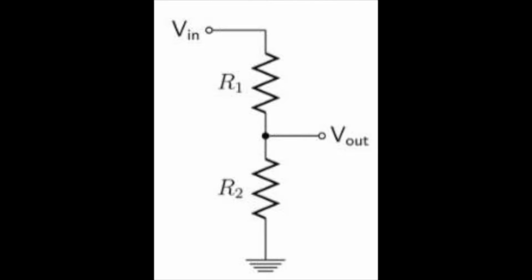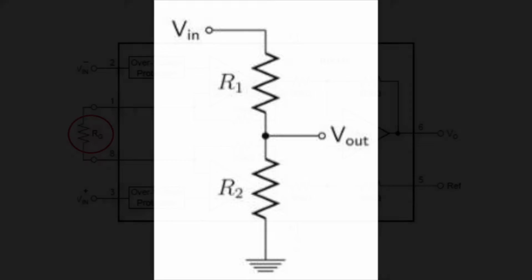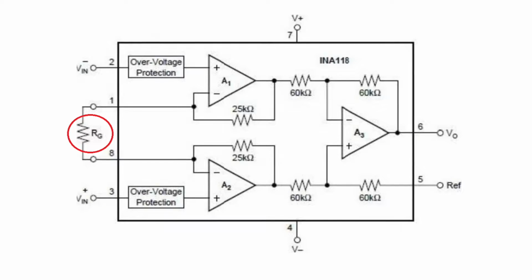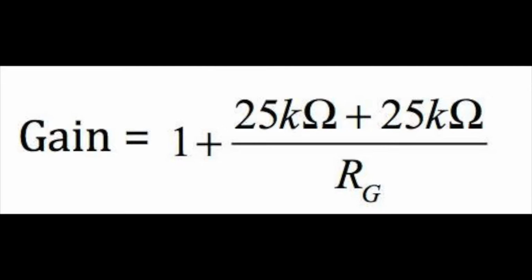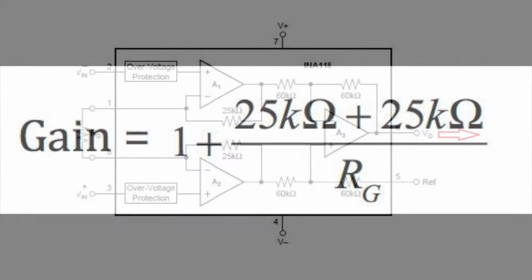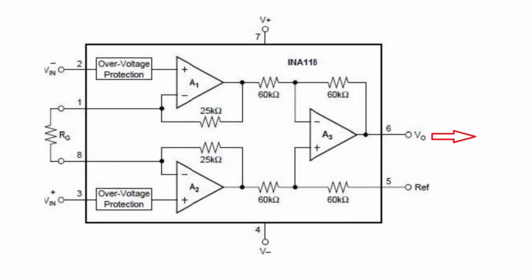We could choose any resistance for R1 and R2. We chose 100 ohms. Then we connected V_out to an electrode which we placed on our elbow so the circuit and the body were both grounded. We found the value of Rg, which is the gain resistor, by using this formula. We put the total gain of the amplifier as 10. Then we continued from V0.